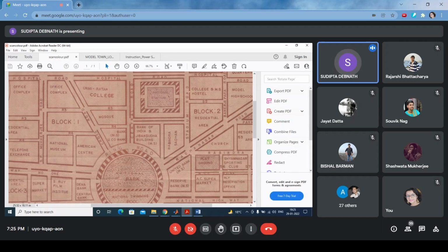Now, if you are given one crossing, you can put 4 street lights, here one, here one, here one, here one, and in this way you can put the street lights. It will be better to put street lights at the crossing. Put 4 street lights here, then go on adding after every 100, not more than 100. The spacing between two lights can be below 100 but not above 100.